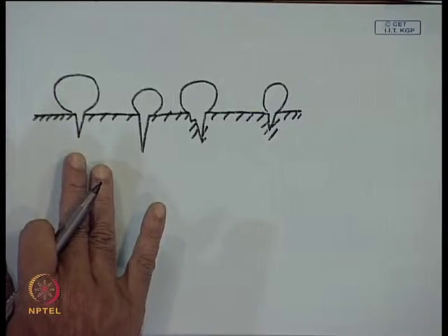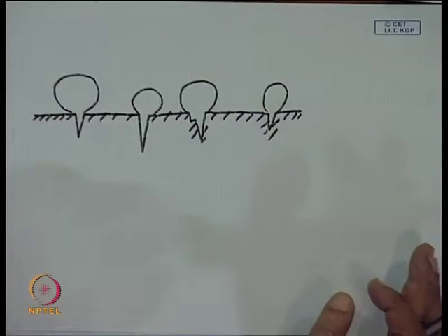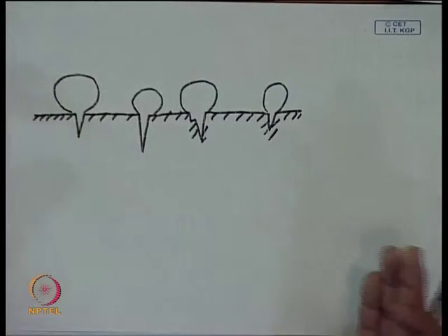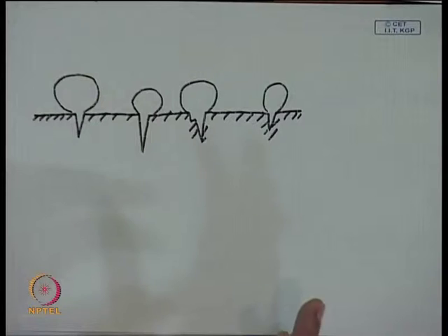Now, basically in this isolated bubble region, one bubble is not influencing the growth or the heat transfer process of another bubble. That is one of the assumptions. So, that means you can do the analysis based on what is happening to a single bubble. That kind of analysis we have already done, and we will discuss some more regarding the same process. That means there is an isolated bubble which is growing, and then there is a heat transfer process and phase transfer process.